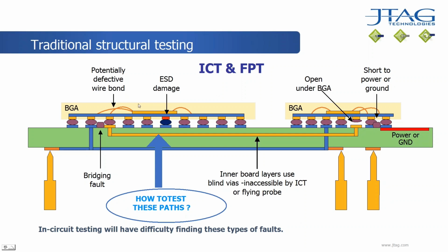Because boundary scan is embedded in the silicon wafer of the chip, you see the little orange block at the top, and using that test access, you could drive a signal through a bond wire, through the ball of the device, through the track, and then along and test for continuity. And obviously, if there's no continuity, we see a test failure. So really, that was one of the driving forces, to improve accessibility on these types of boards.